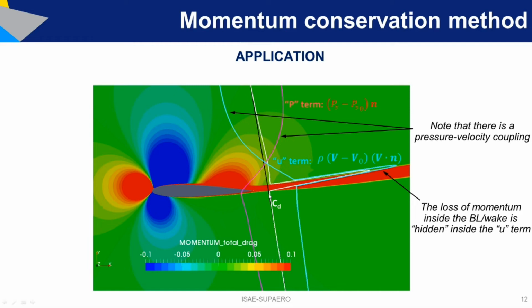And that's why, as you can see, drag has a peak there related also to the velocity deficit. So as you can see, this peak is mounted on top of a baseline distribution that continues here. So we can realize that there are two physics overlapped.